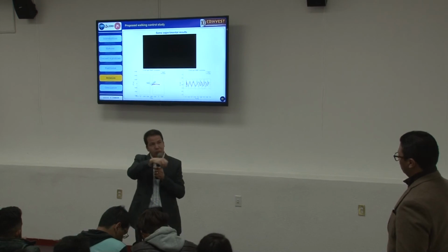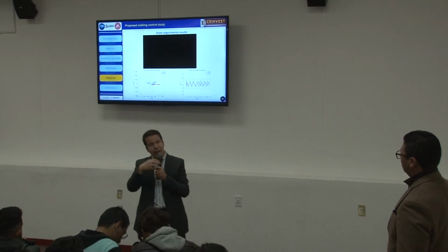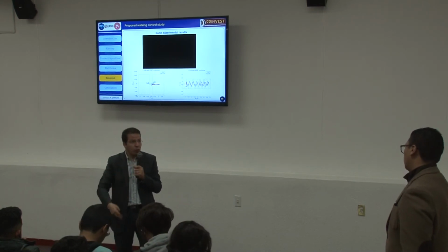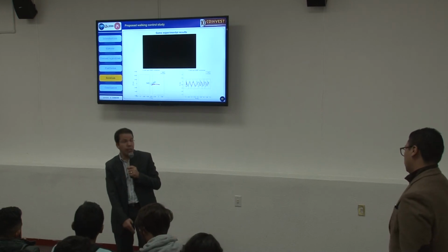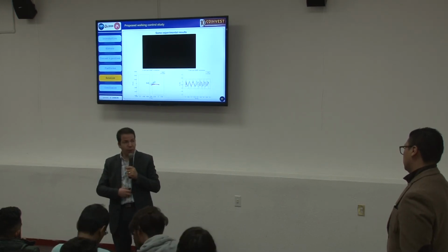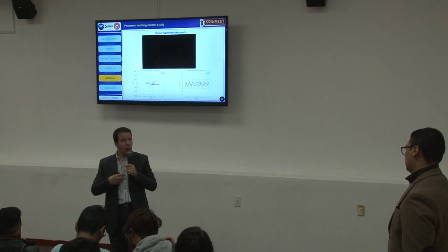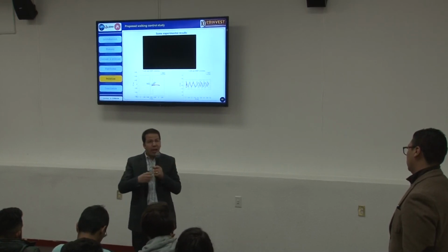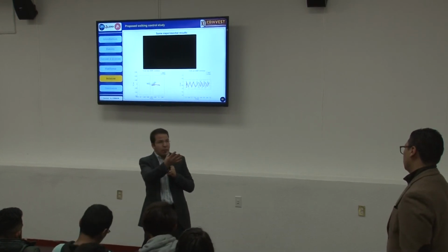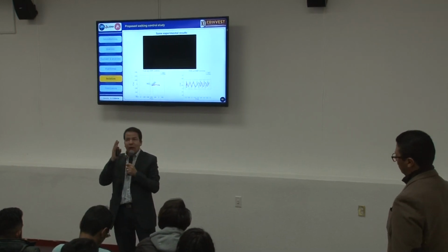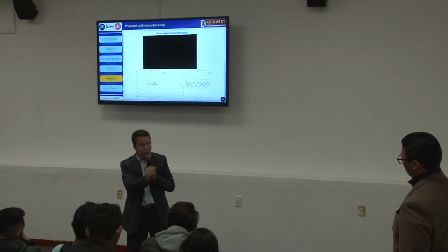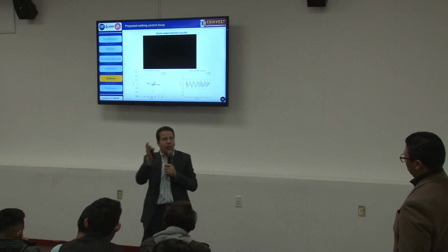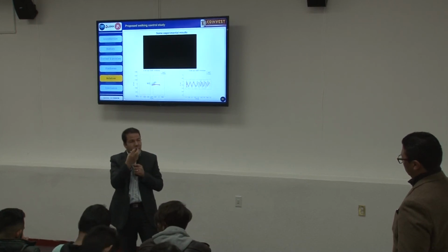And the other particularity of the controller is we are using the kinematics and the dynamics. Through the Jacobian and so on, you specify your task, what you want to do. This is just between the feet coming from the human motion capture, the center of mass, and the joint angle, the torso. All this information is introduced in the kinematic part of the controller. But if you do this, the limit is the stability. It will not be able to keep the stability because we have nothing telling it that the CMP should be here or here. So we add another loop, which is dynamic. In this case, we obtain a kinematic dynamic controller.